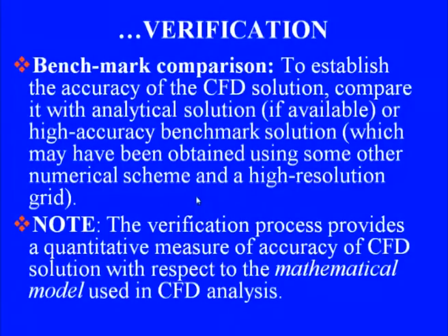Now, please note that this verification process provides us a quantitative measure of the accuracy of CFD solution with respect to the mathematical model which we have used in CFD analysis. It does not give us an estimate of the accuracy vis-a-vis our real life problem. We have just established how close the CFD solution is to the exact solution of our mathematical model. So, that is what we establish through verification process. So, let us have a look at one simple example which we have done in our group.